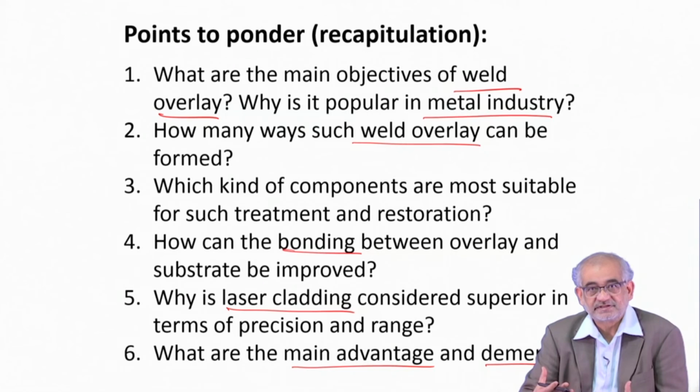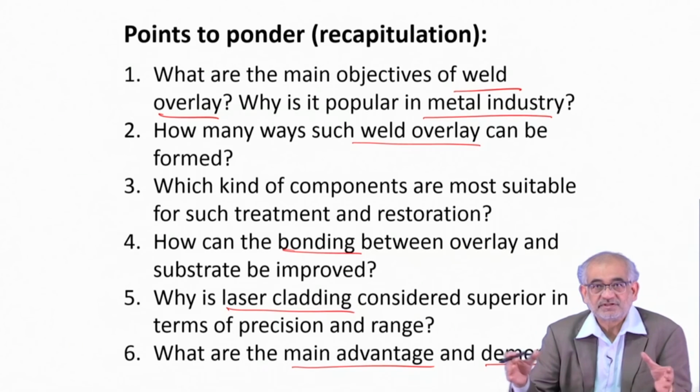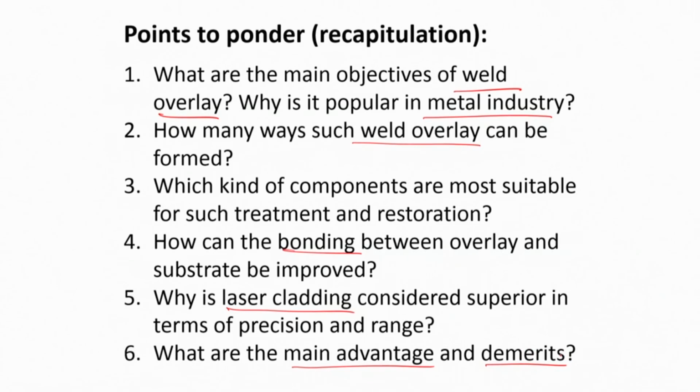then the speed at which you move the material, the substrate. And you also have to make sure that since the bead size is much smaller compared to the total surface area, there has to be surface integration, and there also has to be certain overlap between one layer to the next layer, so that there is uniformity in thickness, composition and properties. So this is a very, very useful industrial practice for surface engineering purposes, with wide ranging applications for various kinds of industries, from automobile to petrochemical to manufacturing, precision manufacturing, and so on and so forth.